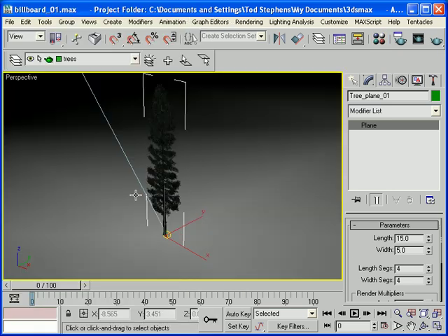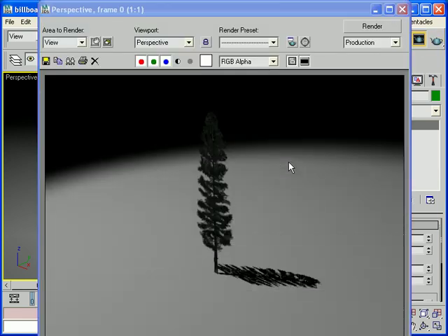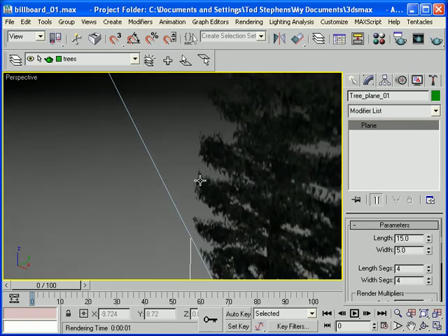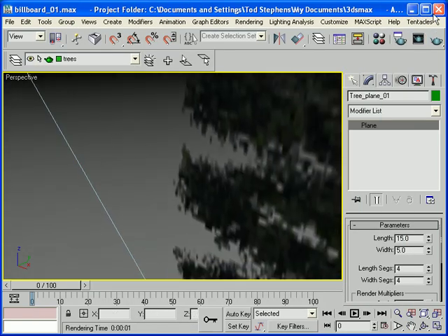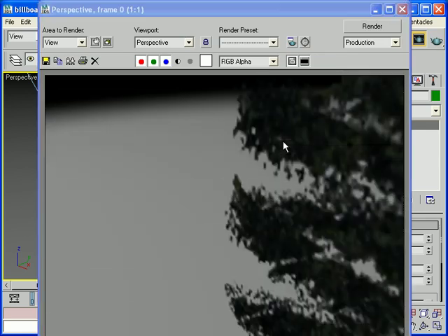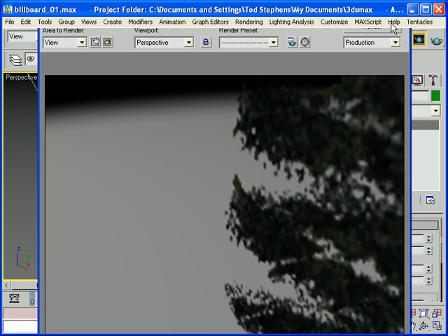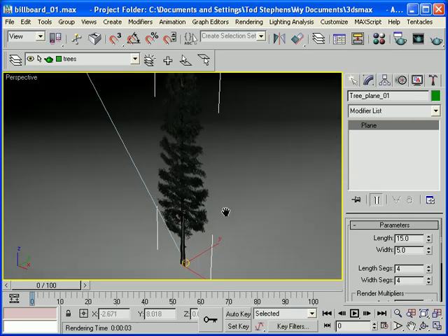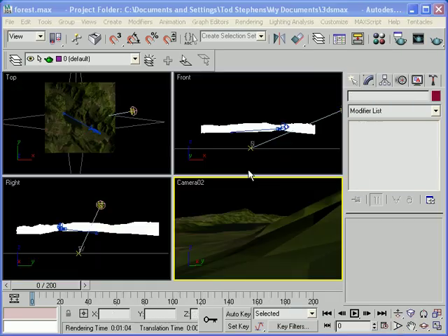So I'll render that out. Again, this is for a little more of a distance. Out from a distance, you'll have a render of a bunch of trees, and I'm going to have several thousand of these trees put on that surface I was working on. So you can see as you get zoomed in here, pretty obvious to see it's just a flat image. But we're using this as just kind of a quick way to make a forest for more distance areas. You don't want to actually create the 3D geometry in your scene.